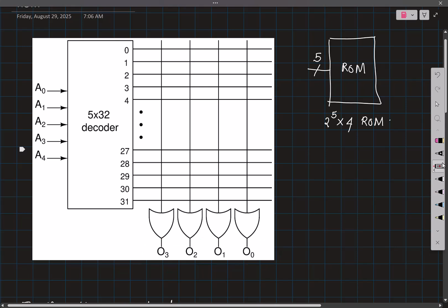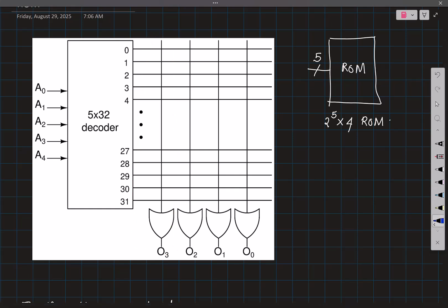Right? Okay, so like I said, you will have only one of these wires going high at a time, and then you have this gigantic 32-input OR that is ORing all of these. In particular, this connection, for now just understand that it is going to be programmable, wherein if I put a cross, then it is shorted. If I leave it without a cross, then it is simply not connected. It's just 2 wires passing by, they are not shorted. So let's say I do something like this.